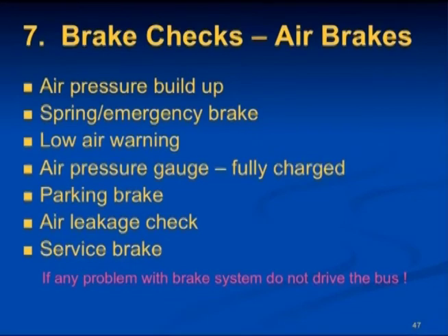When spring brakes are on at the post-trip, the bus should not move when you start the bus. The low air warning buzzer will sound until the air pressure reaches about 60 psi. With the engine running, build the pressure until the low air warning buzzer and light go off.